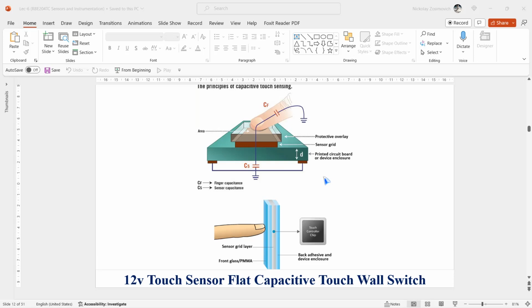When the top electrode shifts to an off-center position, the coupling becomes asymmetrical, resulting in an output signal. This signal is proportional to the displacement, with a phase indicating the direction of the movement. Using the simplified model in figure B on the bottom part of the slide, it is easy to verify that the current through the readout electrode satisfies the following.